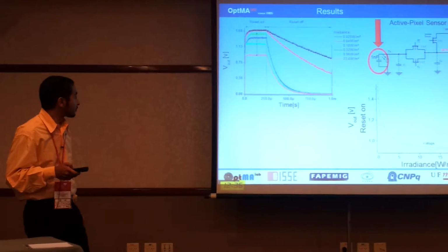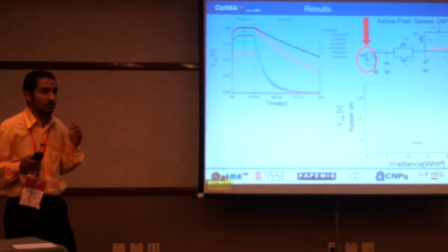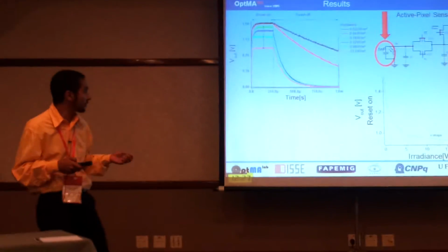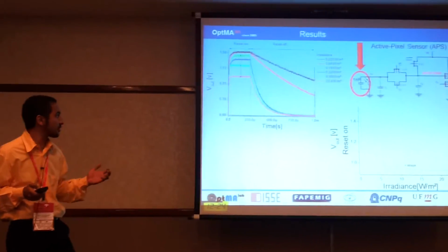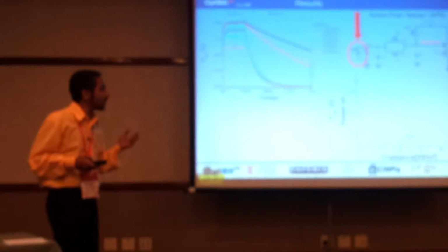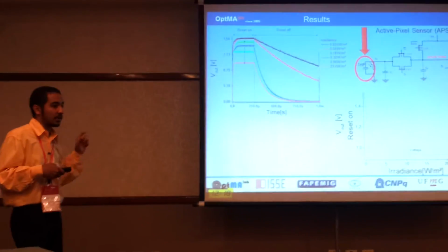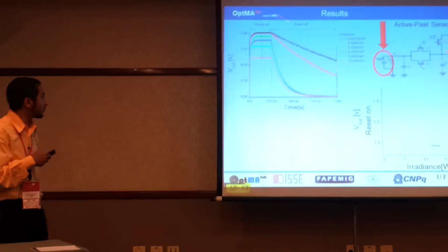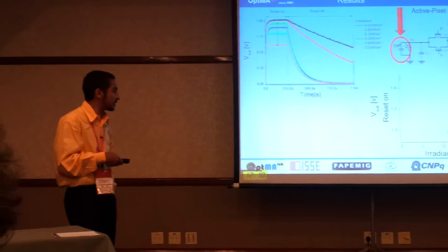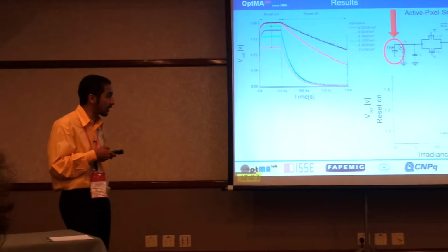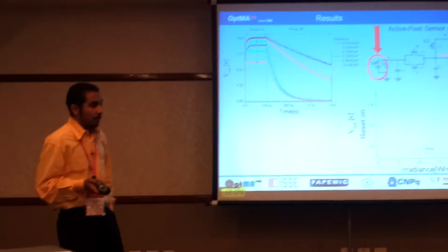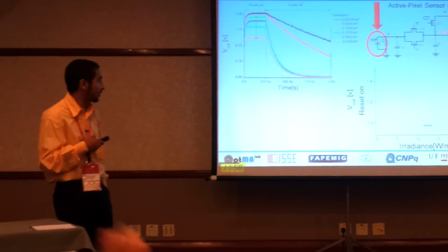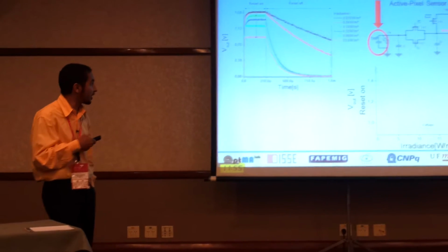Then, to modify the proportionality factor of this discharge, we need to change the RC constant. So we associated a 1 nanofarad capacitor to the LDR and measured this response. In the period of reset on, we have basically the same response in the logarithmic mode, and in reset off, we have a small decay in the linear mode.